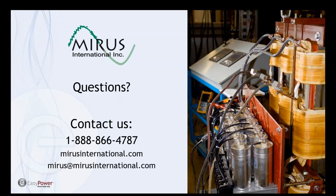Okay, so thyristor rectifiers control the firing of the diode bridge. If they're trying to control the DC bus voltage level, and to lower the DC bus voltage level, they'll delay the firing of the thyristor. And so the voltage won't be present and it won't switch to the other phases when it would normally switch.